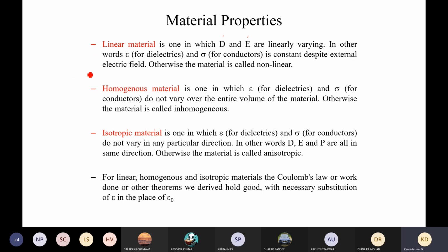But as of now, there is no truly linear material available in the world, it's predicted, because this dielectric constant is always subject to the electric field. That is why if you take any capacitor, with respect to the applied voltage there will be a slight increase. And this increase is often considered one of the error sources of present-day electronic circuits.